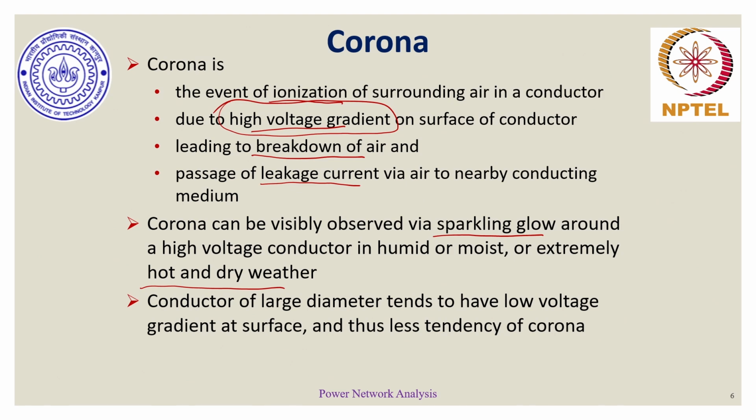So, to have a trade-off, we expect as electrical engineers that the conductor should have a smaller diameter, but then a smaller diameter would increase the surface area, so the diameter should be as large as possible, so the surface area goes up, but then that would increase the cost of the conductor and make the mechanical strength a concern. So to reduce corona loss, bundling is one such measure, and that's the reason why two or more conductors are assigned for a particular phase conduction.